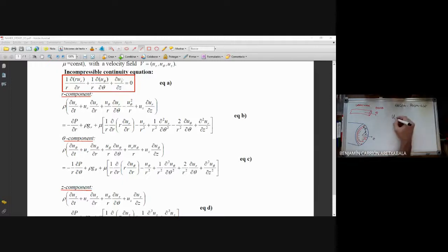So we're assuming u r and u theta are zero, and those are always zero. Also, we want to solve a steady flow, because adding time on top of everything just makes everything more complicated. So steady flow means every derivative against time is also zero. With that in mind, we can start discarding terms.